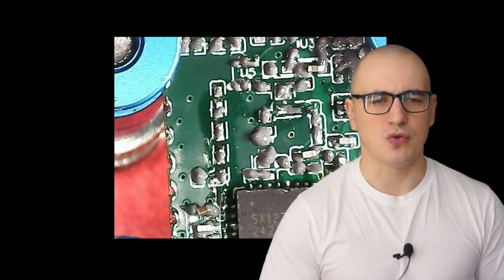First, I implemented a test application to test a connected LoRa module. It checks the correctness of the microcontroller unit configuration of operation, values of registers after reset, correctness of FIFO buffer writes and reads, SX1278 configuration for reception, and configuration of SX1278 for transmission.